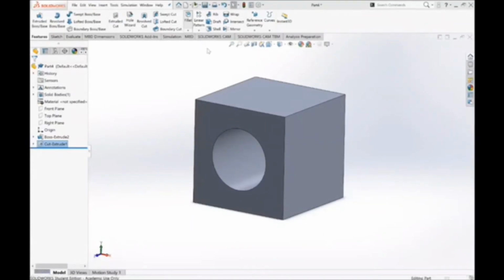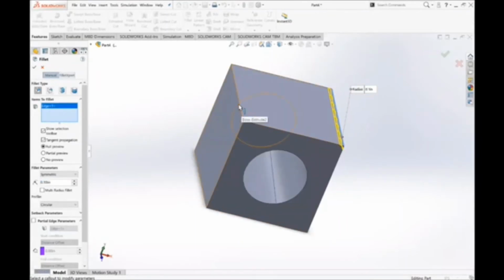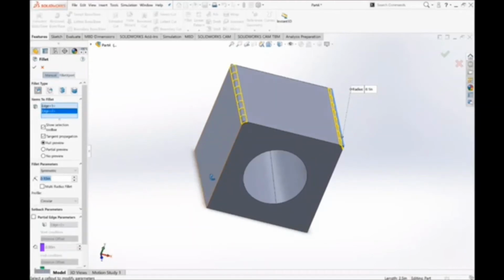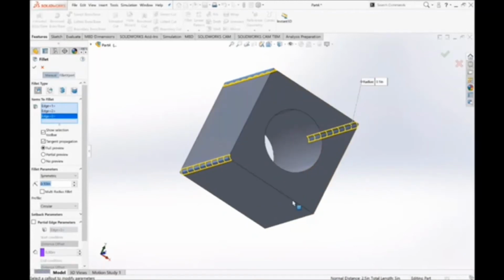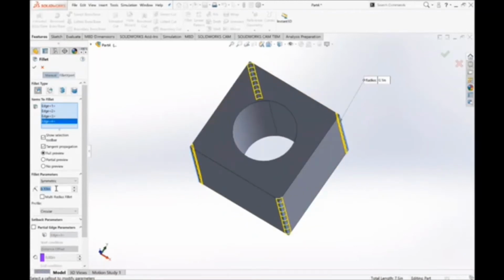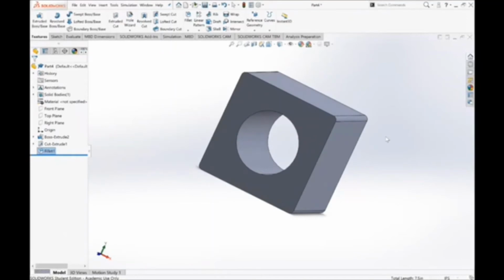And this fillet feature just rounds the edges of your part. So here we will be hitting the square's edges, and then once you hit these, you can decide your radius, which basically shows you how big you want the edge rounded to be. So ours is 0.1, which is a good size. And here you can just see it has rounded the edges.